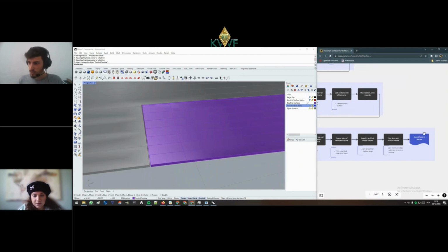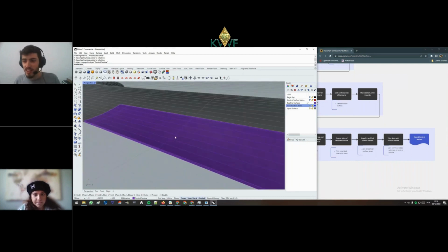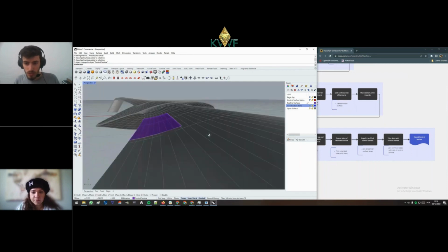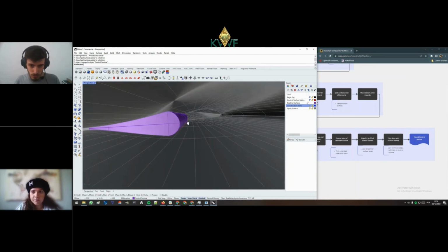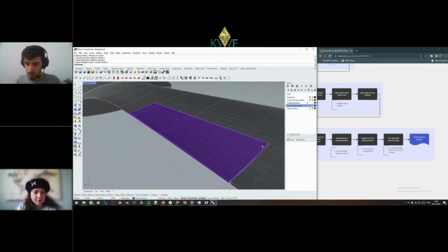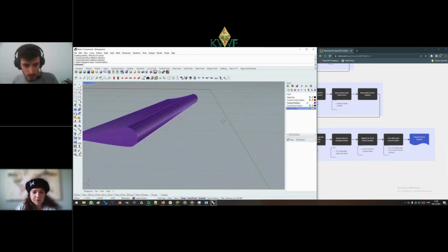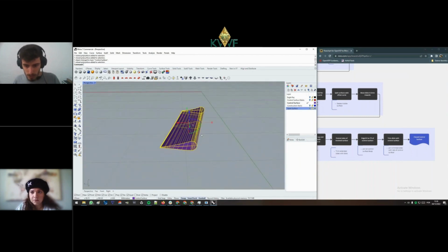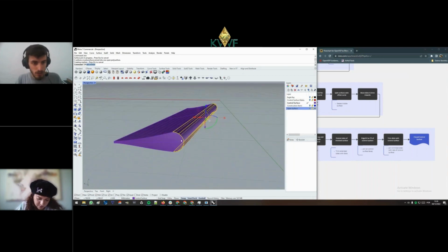And now it's actually the end of the flow chart here, but there's one additional step that we worked out kind of last minute, which is to close the wing surface so that we can have a closing here before the leading edge to house the rotation. So I'll do that right now. I can hide the open surface of the wing. I can explode the control surface again just to isolate these surfaces. I will join them, and I can do an offset surface,